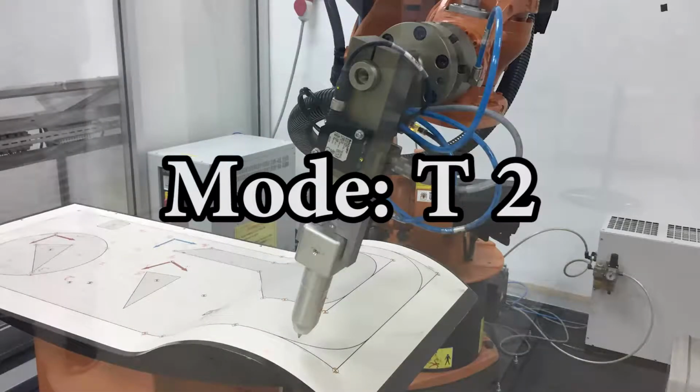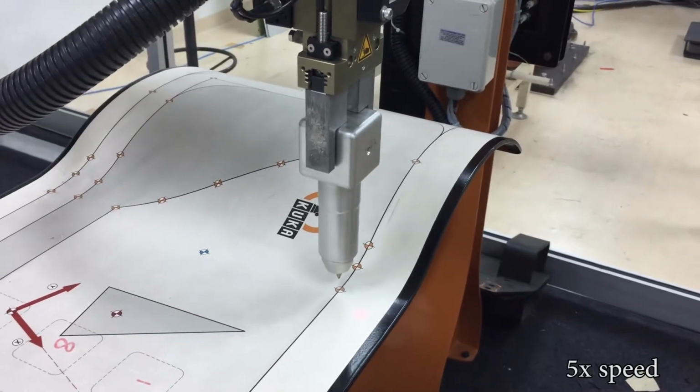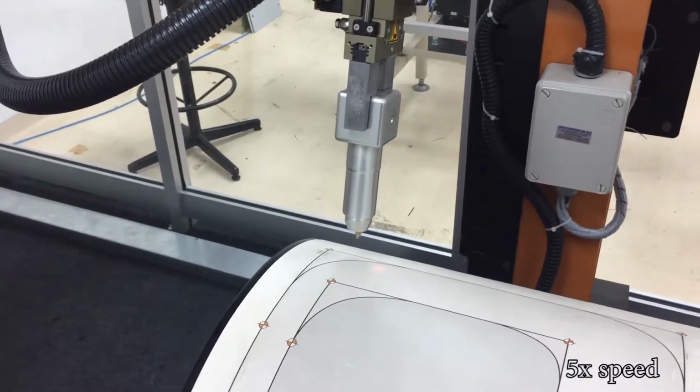Turn the mode selection key to bottom left to select T2 mode. The purpose of T2 mode is to execute the program at higher velocity. Unlike T1 mode, it is safer to run the program in the range of 30 to 50% of maximum velocity to protect the tools.